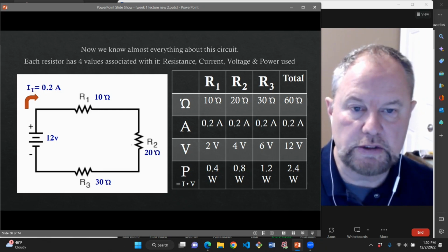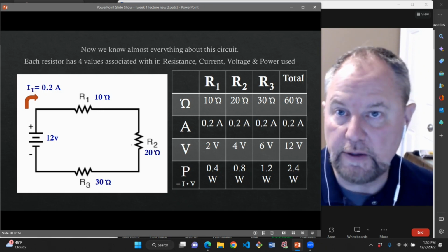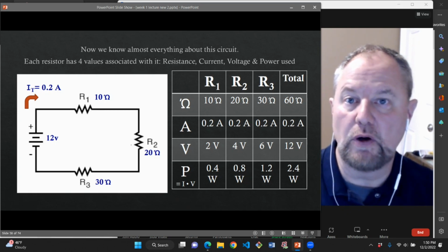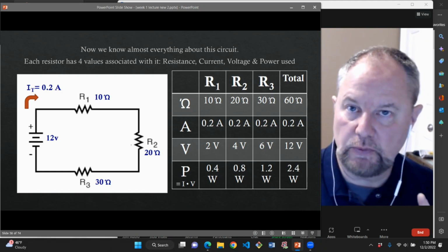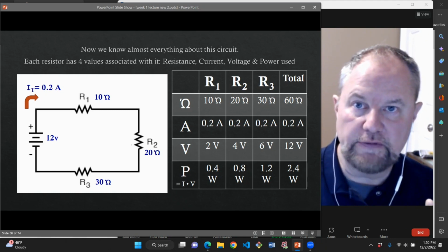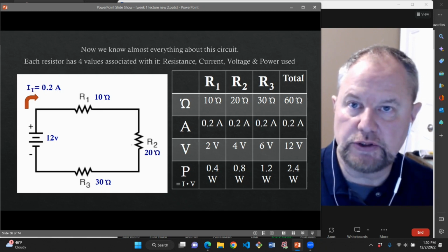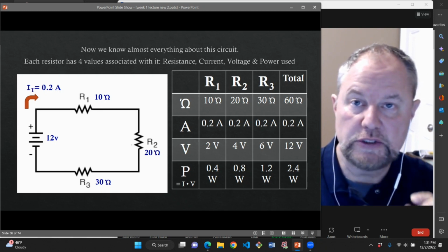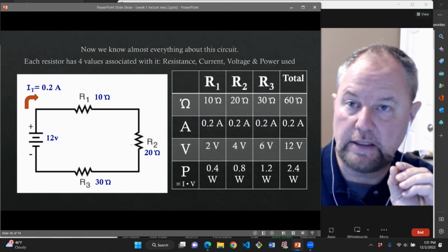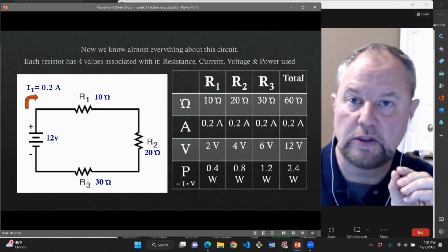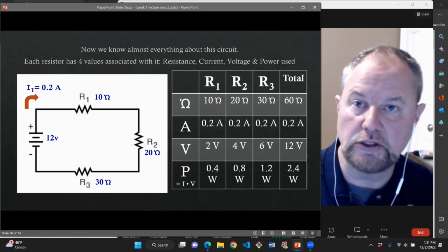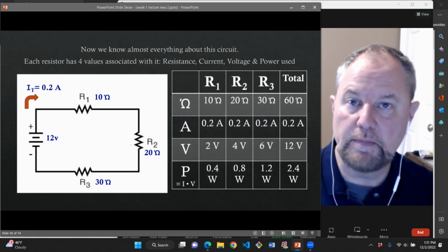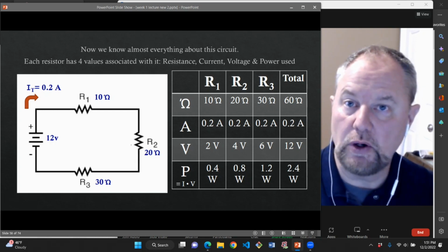Now, one thing you can notice is that with resistors, when you're buying them, you buy them for a particular ohm rating, right? You also need to buy things based on a rating of what it can handle, how many watts it's able to consume. Because some resistors can be very, very small, and they will get overloaded if you try and put too much current through them. You can get resistors that are the size of my thumb that will handle a large amount of current. So you do want to buy your resistors based on not just the ohm amount.